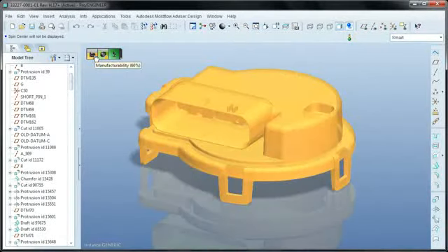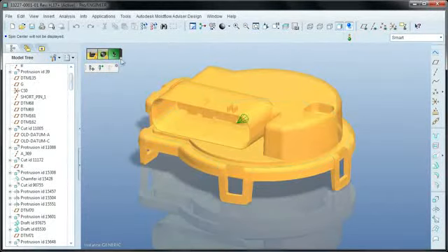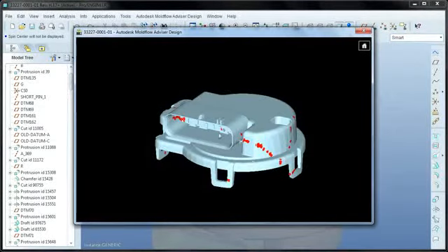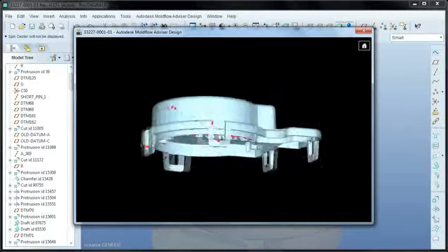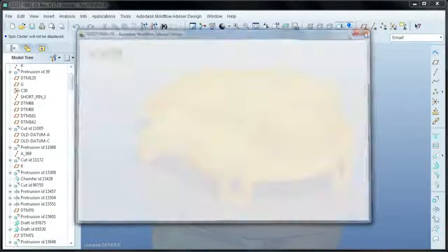Next up is weld lines. The result is calculated from the real-time filling analysis that you saw earlier. So with this alert, you have the option to pull up the animation and injection location toolbars. You can adjust the number and locations of the gates to ensure weld lines form in areas of the part where they will not cause visual or mechanical failures.